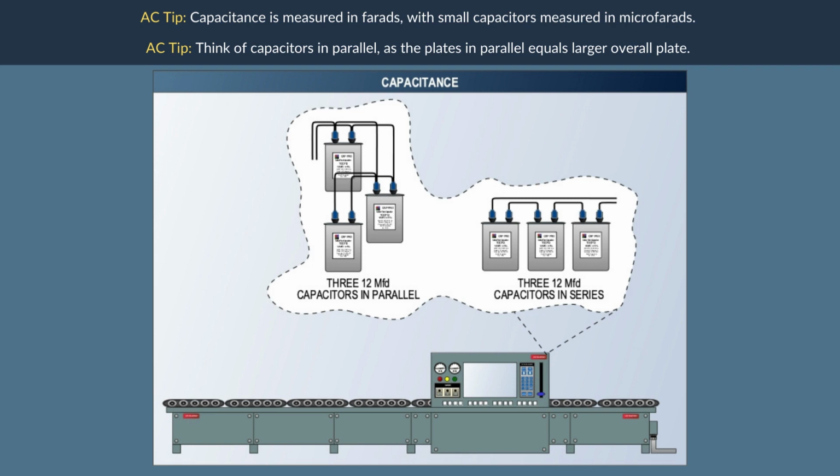The basic effect of a capacitor in an alternating current circuit is to cause the current to lead the voltage. If a circuit could be designed without any resistance, the current would lead the voltage by 90 degrees. This can be seen in the illustration for phase, by the way in which the electrons move through one alternation. Notice, as the voltage rises, the current begins to drop because of the dielectric stress in the capacitor. By the time the voltage has reached maximum, the capacitor is completely charged and no current flows.